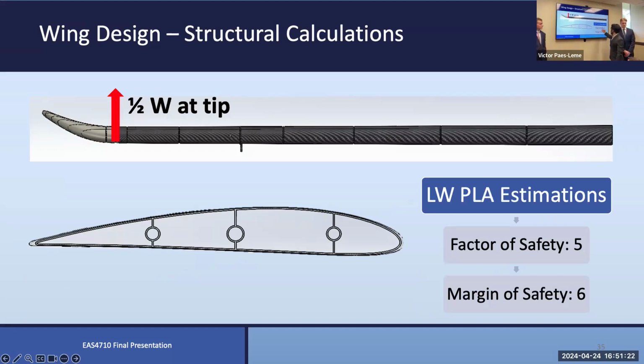That is one of the reasons why our design factor of safety was 5, since those were approximate weight loads that we found for banking maneuvers. As you said, that half weight would be for our cruise. With the use of the FPV camera and the gyro mounted on the plane, we went back and saw that we were pulling more like 3.6 Gs. It is quite a bit for a turn. However, it was still below our factor of safety. This is already a conservative estimate, and it doesn't include the carbon fiber. And we were operating within a greater margin of safety for cruise conditions.